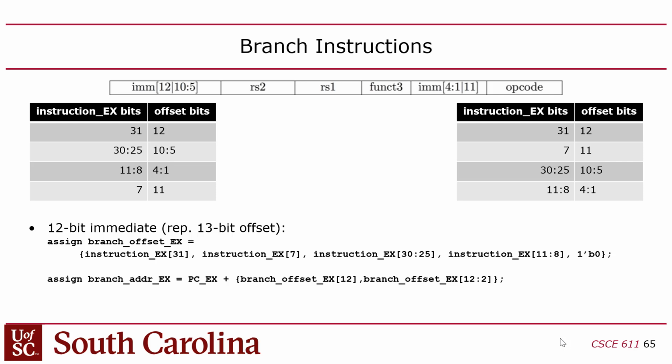And the program counter is PCEX. So this is the program counter for the execute stage, which refers to the address of the instruction in the execute stage, which you have to add in your, right now in lab 3, you don't have a PCEX, you have a PC fetch. So you're going to have to add a delay. You have to delay PC fetch to become PCEX, right? That's just an extra register you have to add. Make sense?